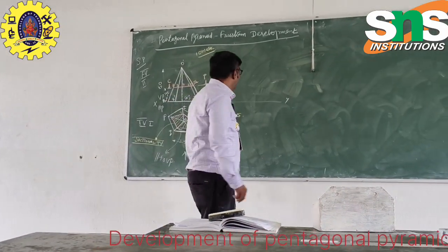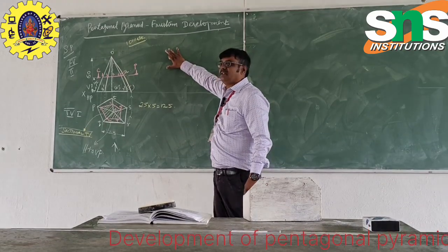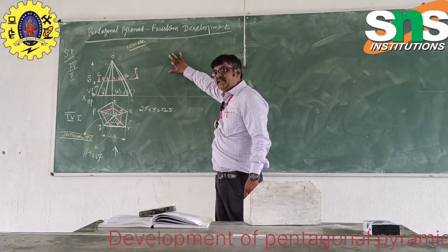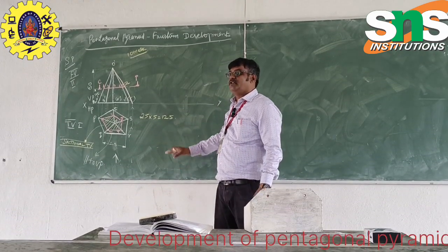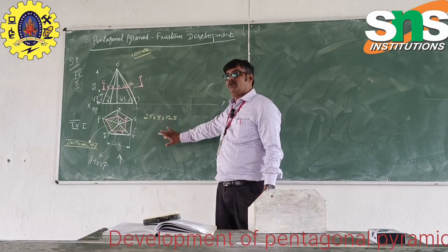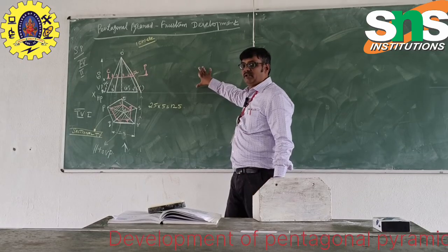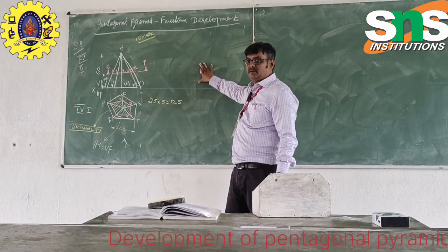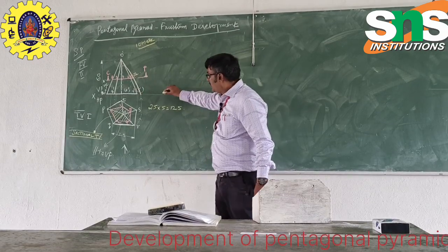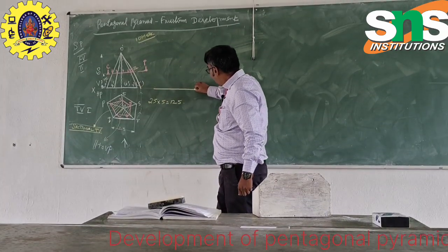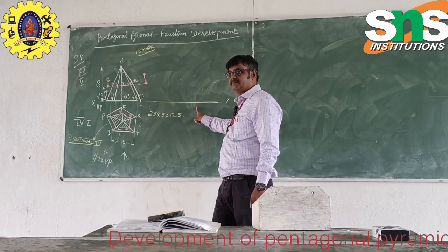Correct. Now, I am searching for space in your drawing sheet. If you have more space on the top over the XY line, you can draw it here. If you find more space at the bottom, you can draw it there. If you do not have space at the top, you can go down because you have to measure the line. My suggestion is to draw this development parallel to the front view itself. Now I am drawing a line which has a length of 125 millimeter.